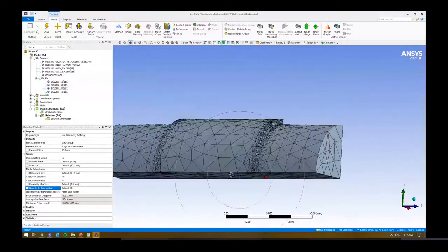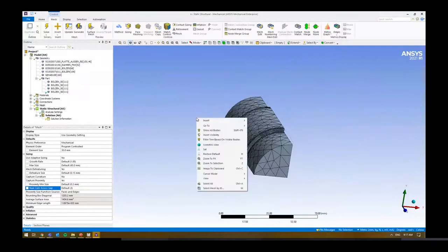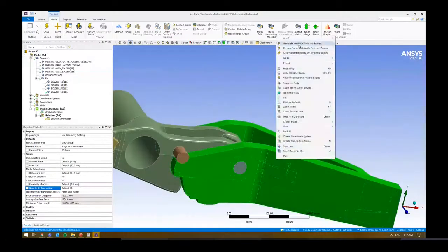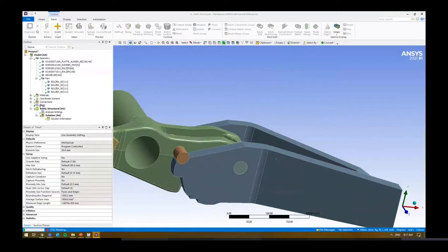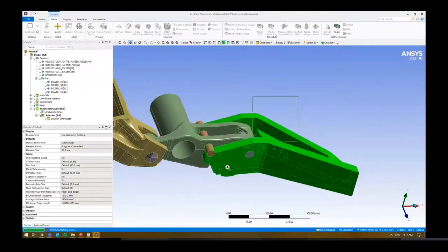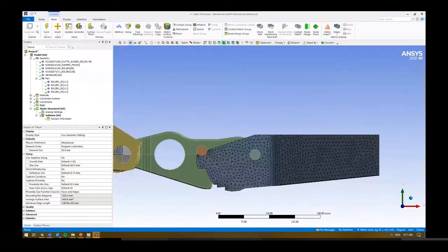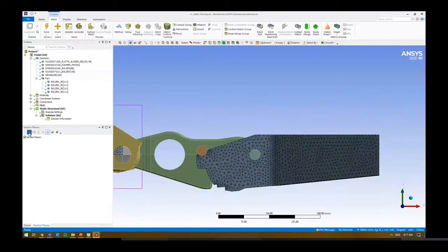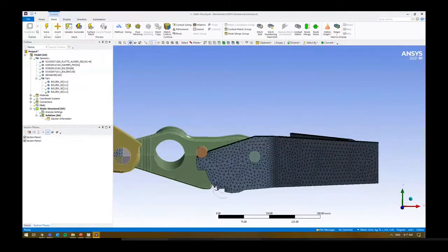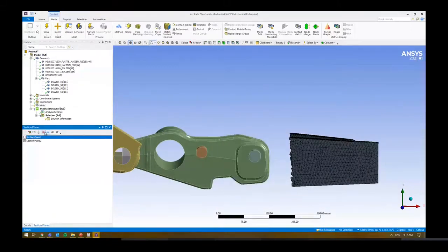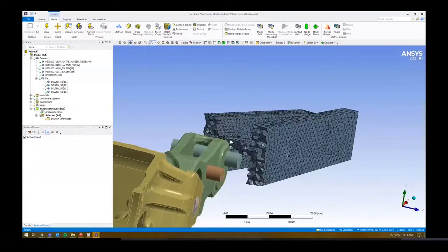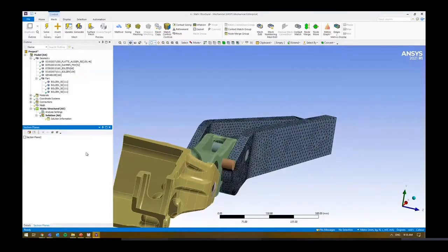Depending on what you want to do, we can start to play around with these types of things. The problem can be, though, if I generate something like this for the whole body, it can really cause us some problems and start to really increase our mesh count. If we take a section through there, section 1, we can see we've got 3 elements through there as well. Sometimes that might be what we're after, and it might not necessarily be.